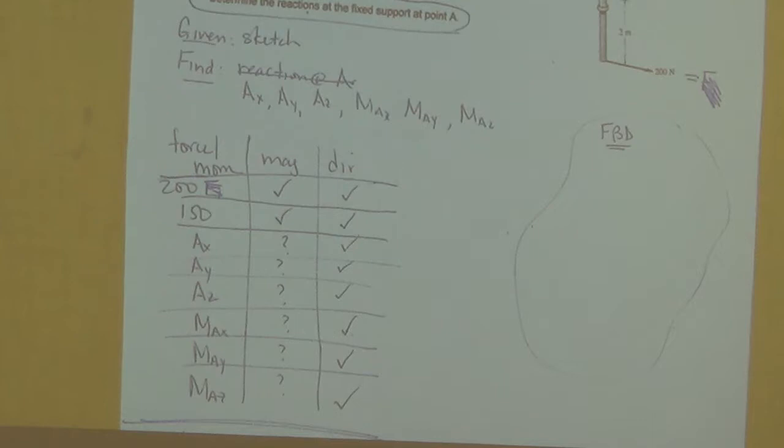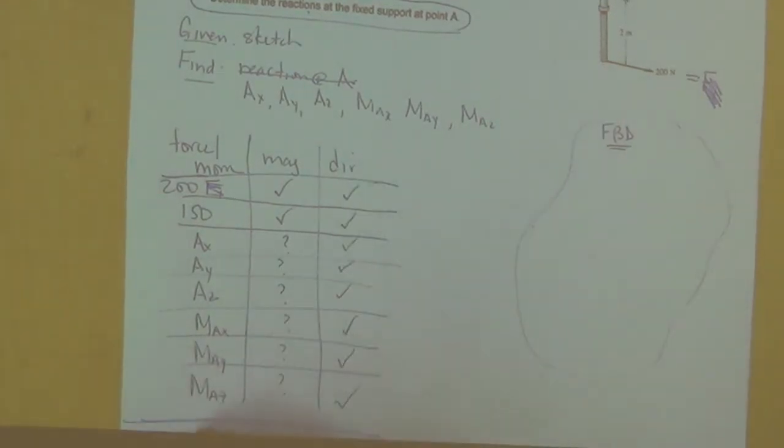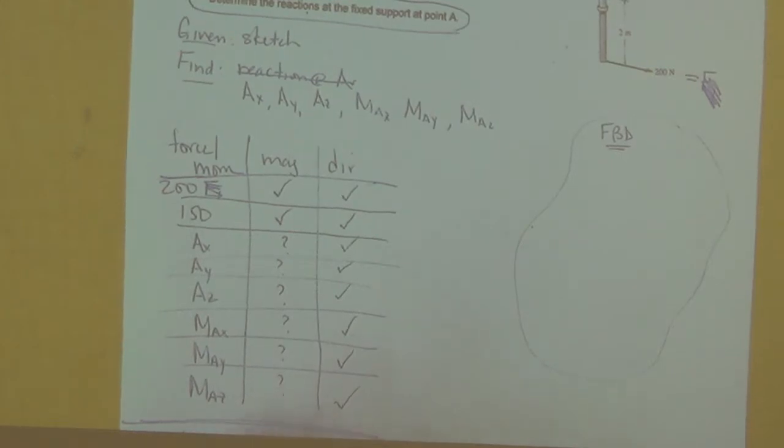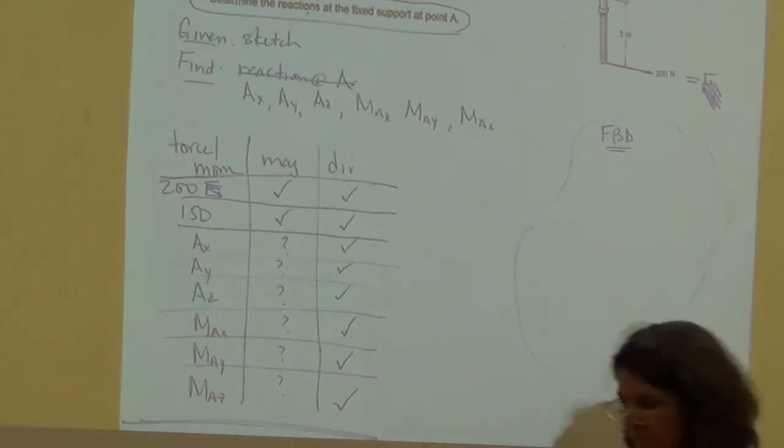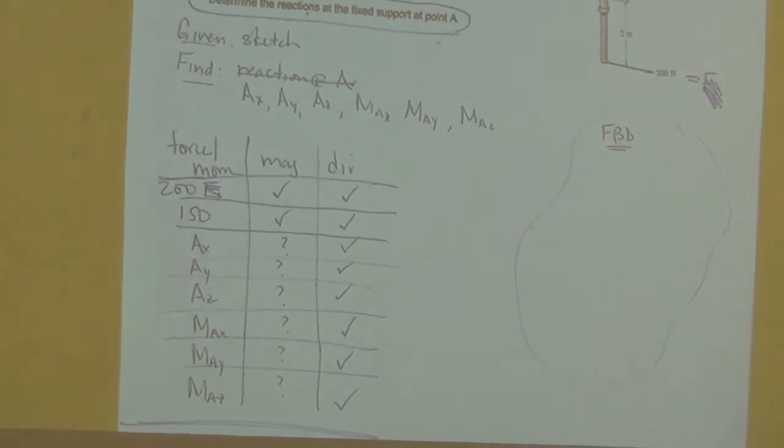Well, you can get the forces in the X, Y, and Z, and the moment in the X, Y. So 6 total, right? So I can get 6 equations from one 3D body, so I only need to analyze one body. Eddie, which body do you want to analyze? Yeah, the whole part.